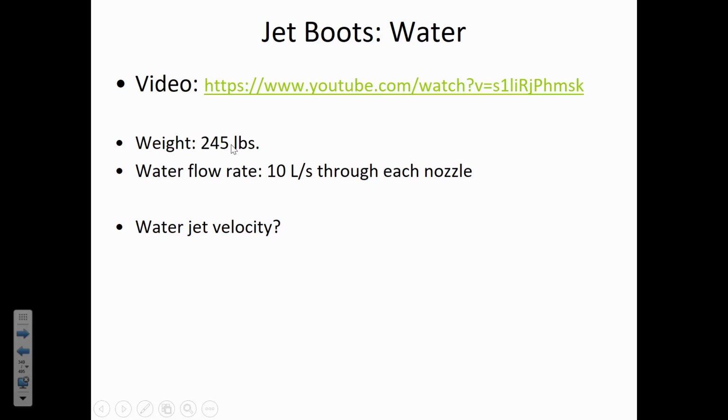All right, so if we want to know the jet velocity, we can use the equation that the force is the mass flow rate times the velocity. When he's in equilibrium, the force holding my brother up is equal to the weight. We can rearrange that to solve for velocity. It's going to be the force that we know divided by the mass flow rate.